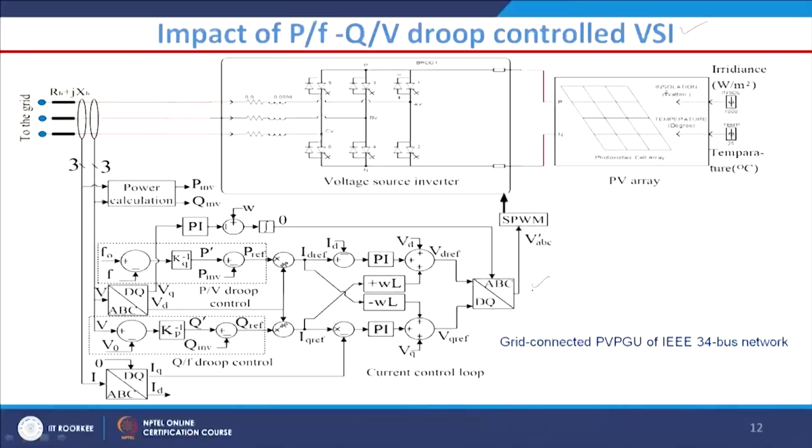Yes, of course, because when we are designing an islanding detection technique, we should test the performance of the technique for different types of control strategies. It may happen that for a certain control strategy this technique will work, while for some other it may not work. So, that is why it is very necessary that we test the performance of the technique for different types of control strategies.